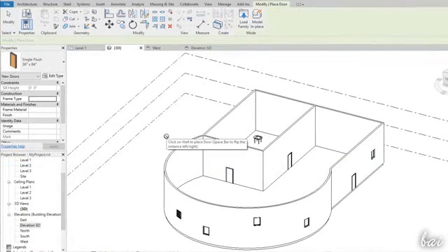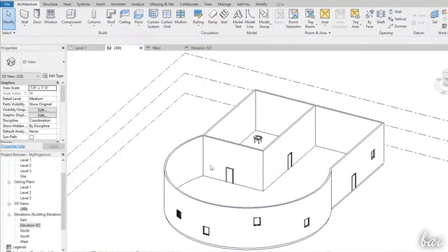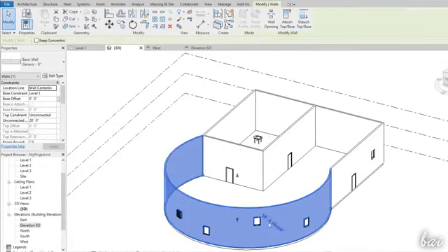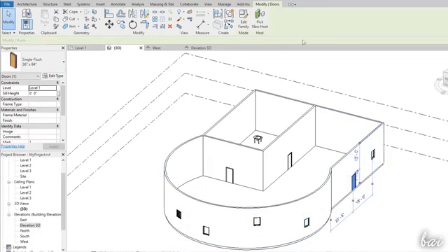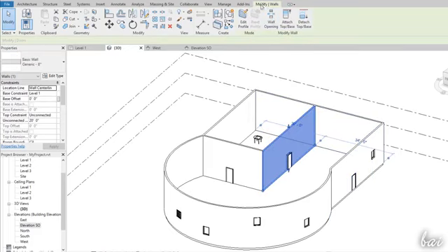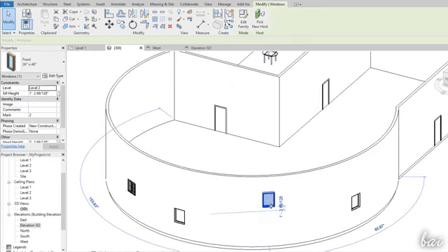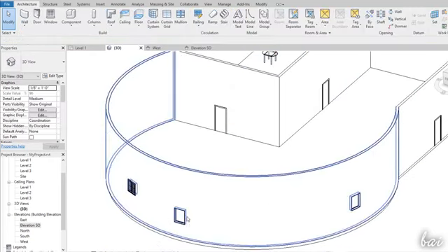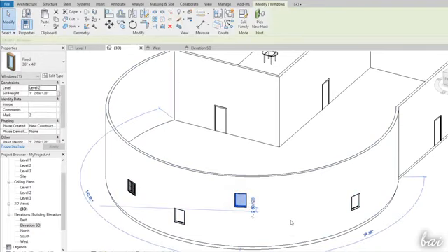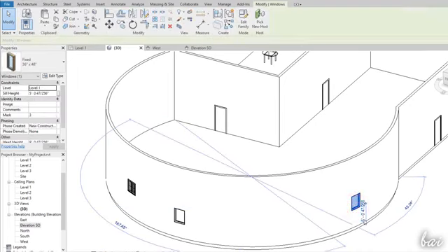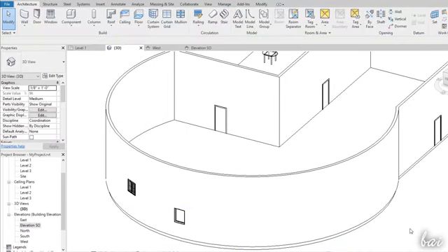When no tools are enabled, you are in Selection mode, where you can click on any floor, wall, or family to select these and start editing them with the Modify tab on top. Once the object is selected, this will be shown in blue color. You can cut, copy, and paste it by using Ctrl and X, Ctrl and C, and Ctrl and V, and delete it with the Delete key. You can also undo any action made by using Ctrl and Z.